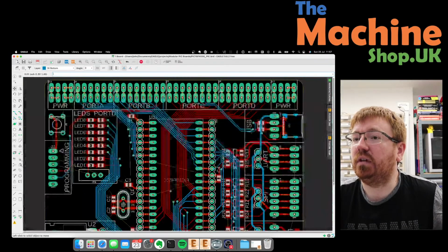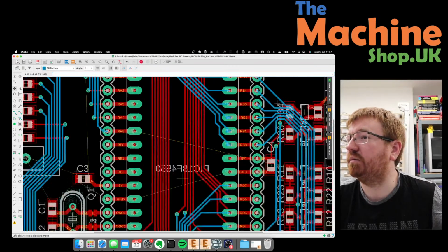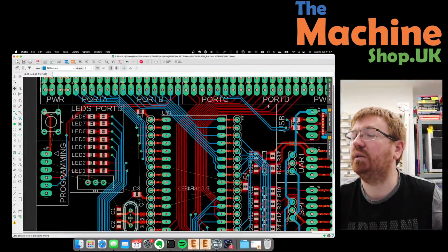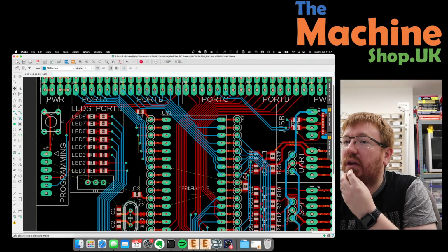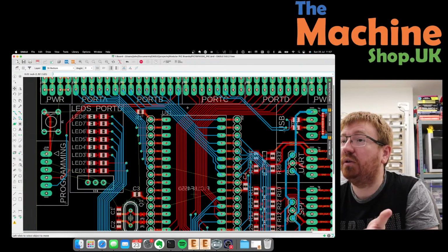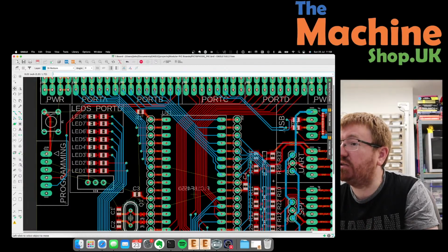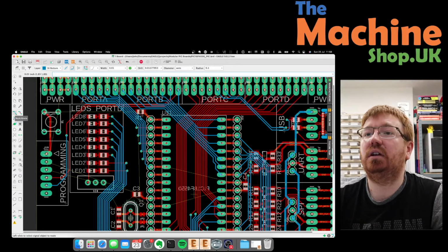Then hopefully I can get... Where is it? RA5, that was it, wasn't it? That's what we're trying to get over to there. RA5 all the way over to there. So, how am I going to get... I can get from there on the top layer all the way to there, change to blue on the bottom layer, all the way to here, follow this on the blue, change to top layer there, bang, RA7. Perfect. That looks good.